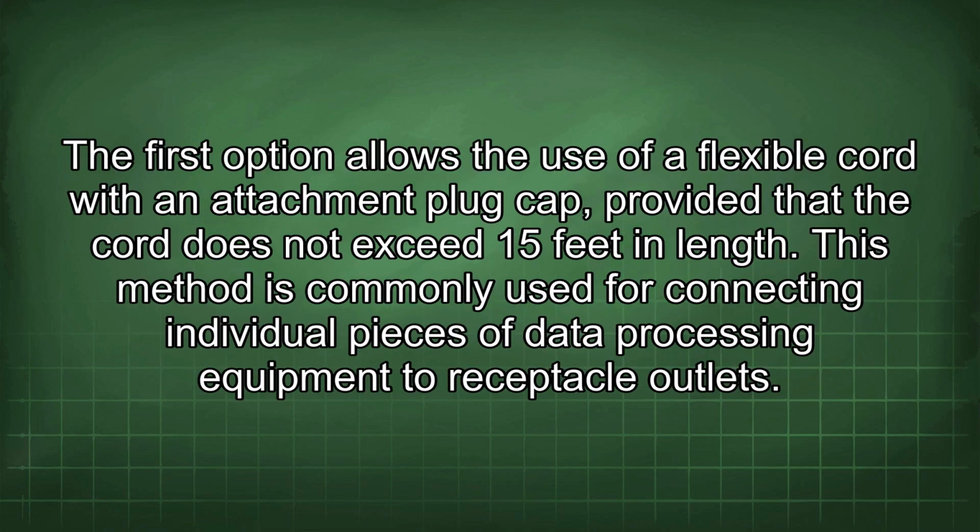The first option allows the use of a flexible cord with an attachment plug cap, provided that the cord does not exceed 15 feet in length. This method is commonly used for connecting individual pieces of data processing equipment to receptacle outlets.